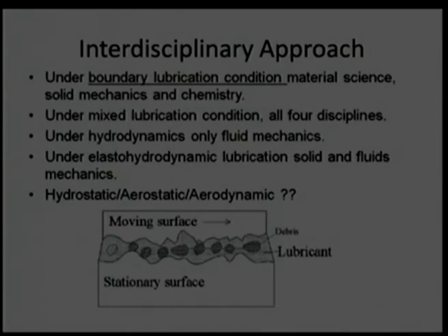In the hydrodynamic case, the pumping source is self-acting, from relative speed in combination with load, while in hydrostatic it is an external pressure which is fed between two surfaces to levitate one surface relative to the other surface. Same thing with aerostatic. In case of aerostatic, we are putting in gas. This gas can be anything, it can be nitrogen, any neutral gas, it can be air also, which is not going to corrode the surface.